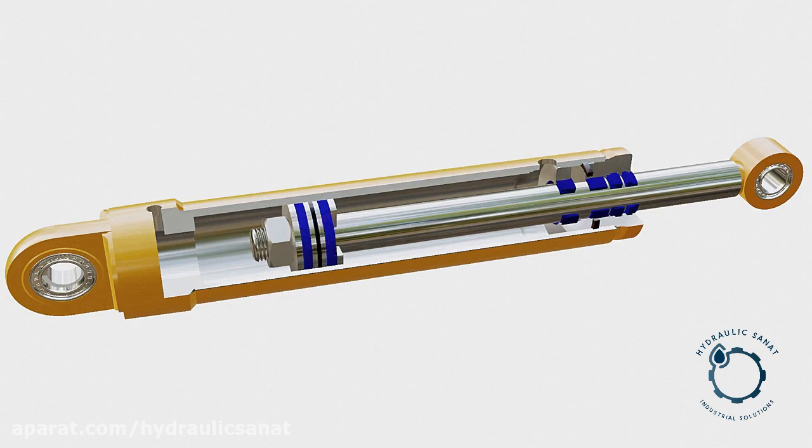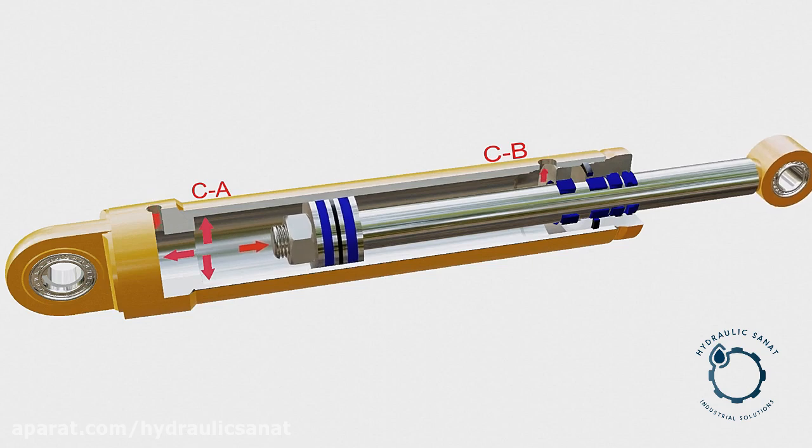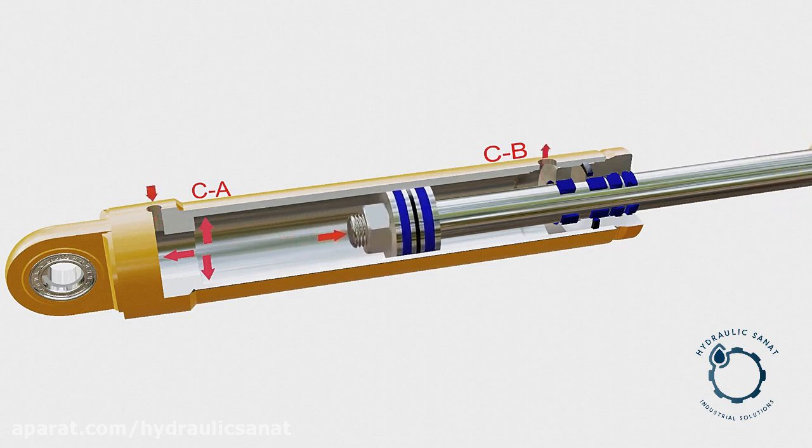Now let's understand the working of a hydraulic cylinder. The model shown here is a double-acting hydraulic cylinder, which means the system can extend or retract by using hydraulic fluid in both conditions. A fluid pumping unit creates flow of hydraulic fluid into chamber CA. Since the chamber is confined, the fluid exerts pressure on all sides in the boundary of the chamber. But in this case, the piston is the only movable portion of the chamber boundary, so, when a sufficient amount of force is developed, it is forced towards the chamber of low pressure. This also pushes the fluid back to the reservoir from chamber CB.